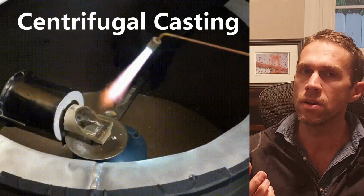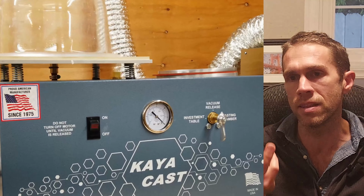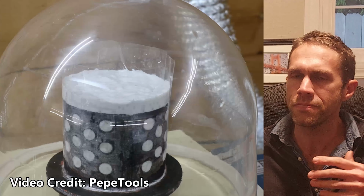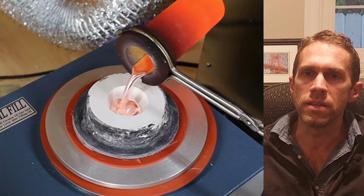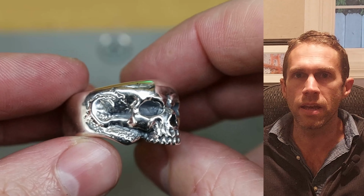These castings are generally done with the metal being pushed in under pressure, either through centrifugal force or through a vacuum, which is attached to the bottom of the flask and sucks both the air out as well as the metal in. Afterwards, of course, the metal is removed from the flask, cleaned, and removed from the casting tree. And then you go ahead and clean up the casting, finish it, add any stones, etc.